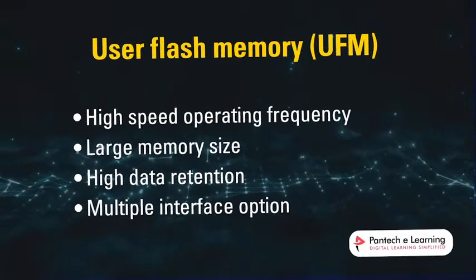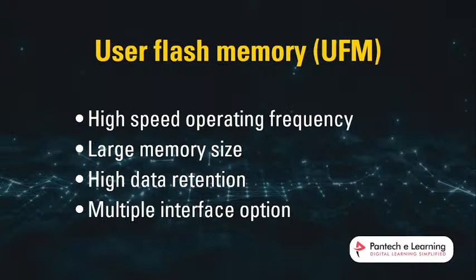And then coming to, I already said, one type of memory is user flash memory. Our FPGA has the UFM, a kind of memory inside the FPGA. It has high speed operating frequency, large memory size, high data retention, and multiple interface operation.